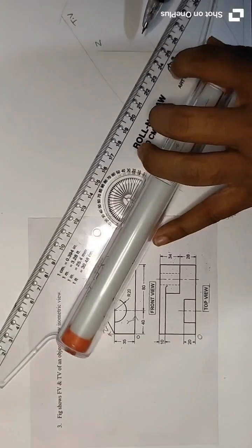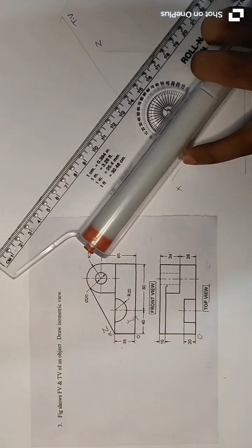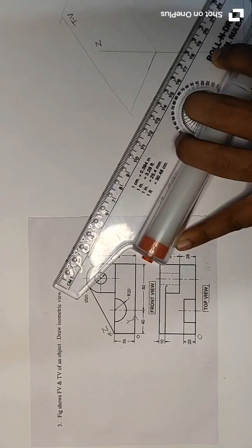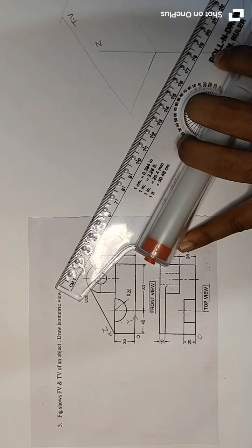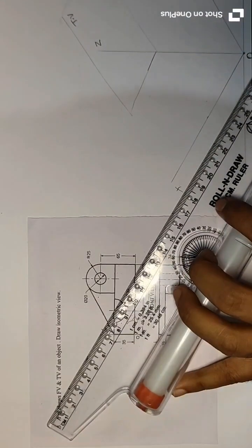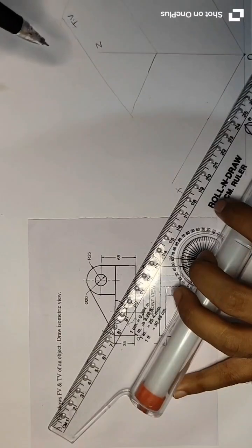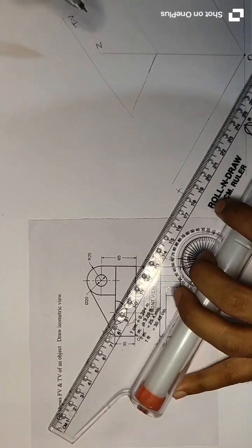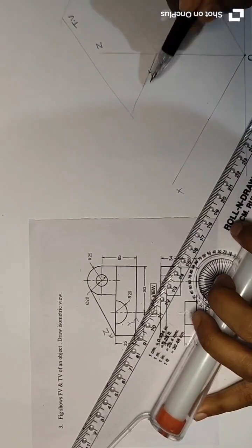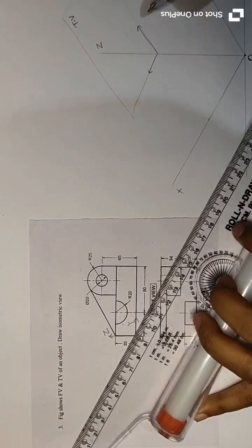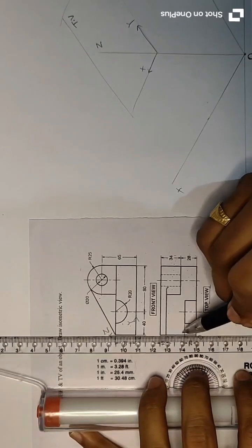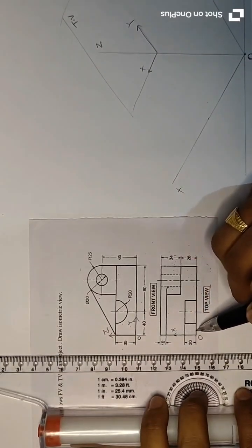And in the top view, suppose the direction of the front view is along this direction. When we look from the top, the direction will be above the front view direction, this direction. Looking in this direction, the x-axis will be a vertical line and the y-axis will be a horizontal line. So for the top view, x is vertical and y is horizontal.